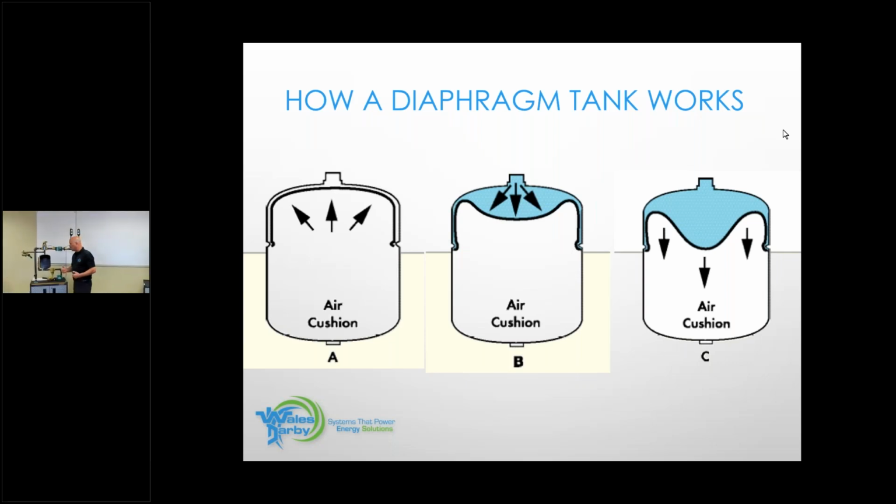But what happens sometimes, what we see in the field is I'll leave my expansion tank at 12 PSI. But because I'm higher than that, 18 to 20 feet, I elevate the system pressure, the operating pressure of the system with my boiler feed valve. Let's say you may like it at 15, 18 PSI, whatever you like. And that's fine. You can put it at 15 PSI. It's not going to hurt anything.